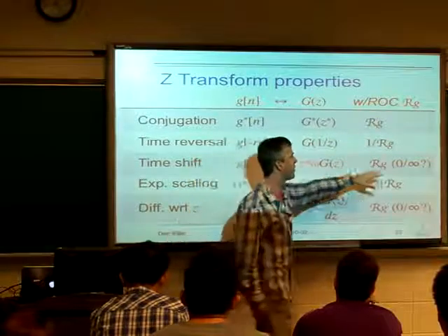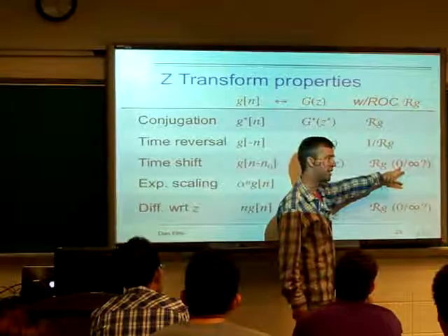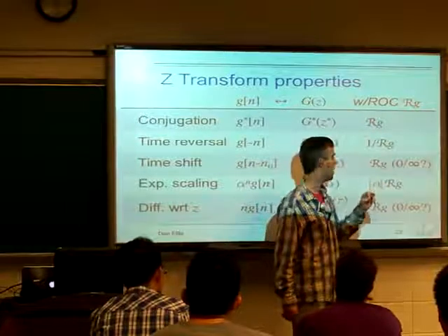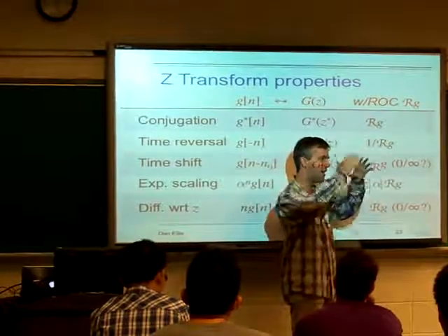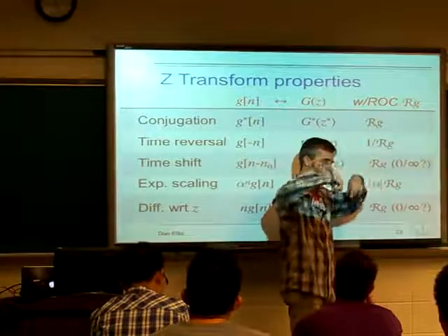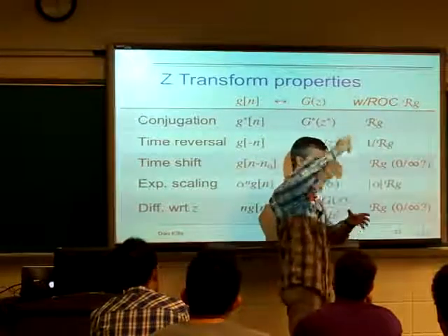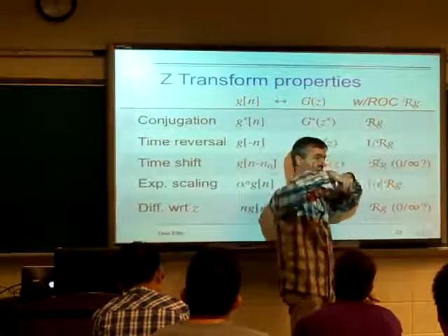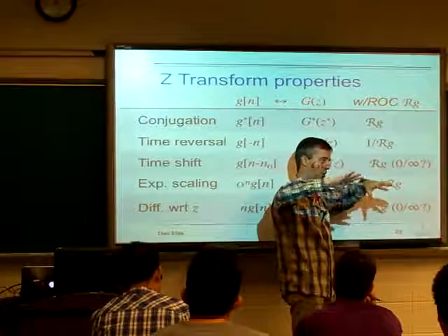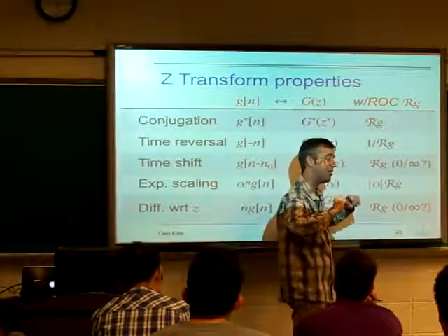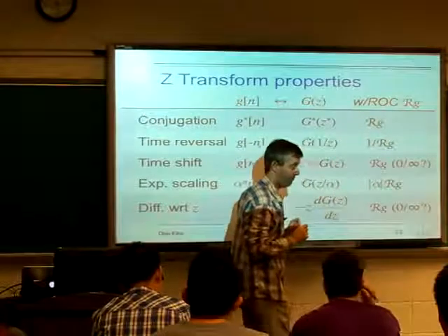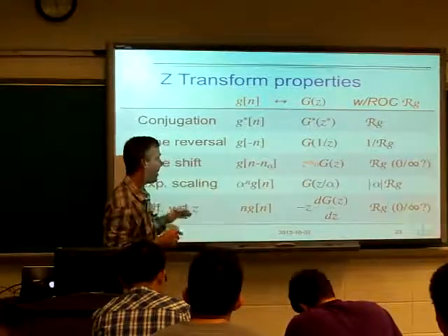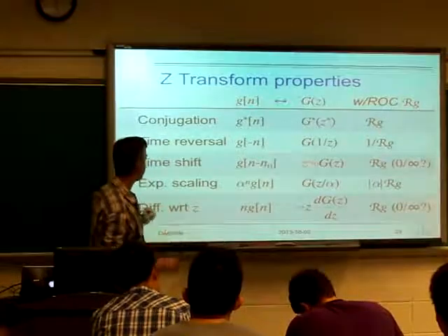And the thing is that extra poles and zeros at 0 aren't particularly interesting. In particular, they don't affect the Fourier transform, because a pole at 0 has a uniform effect on the values at 1. If you've got this pole at 0, it'll push everything close to 0 up around. But by the time you get to the unit circle, it's balancing out, and so it doesn't affect the Fourier transform magnitude. So again, we'll come back to that, but they're less interesting than other poles and zeros.